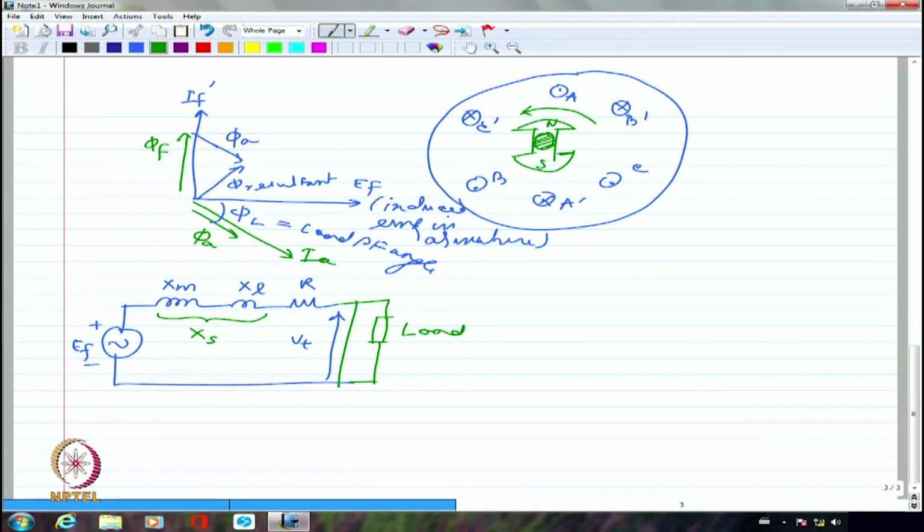high as possible. Even 1% drop in efficiency or 5% drop in efficiency can cost a huge amount of power. We are talking about 400 MVA and so on. So 400 MVA, even 1% is 4 MVA. I don't want to lose out so much of power. So I would like to improve the efficiency as much as possible normally in synchronous machines. Because the larger the machine, we pay more attention to the design to maximize the efficiency. Because the impact of every percentage will be a huge amount of megawatts.